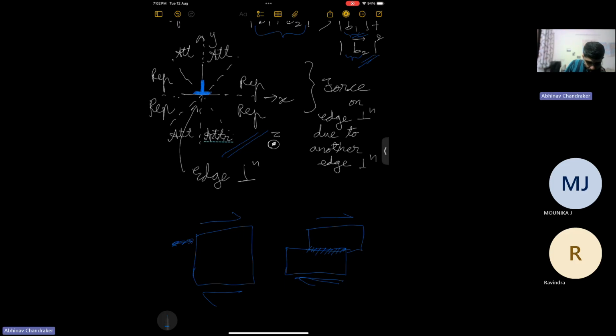This was done by calculating the force on a dislocation nearby. Basically, if it's in this region, where the magnitude of x is more than y, it will repel. And if it's in the other regions at the top and bottom, it will attract.